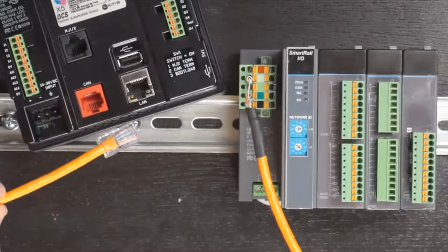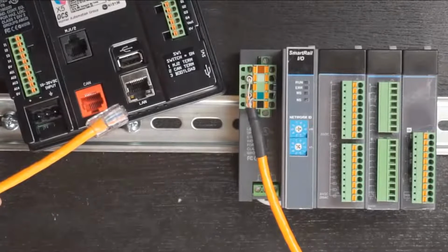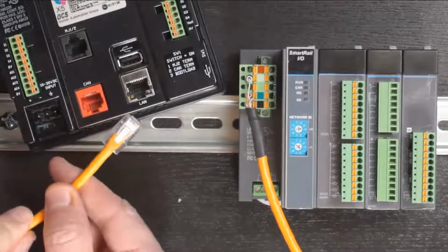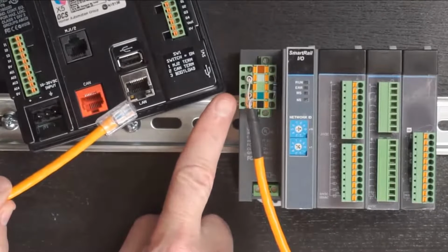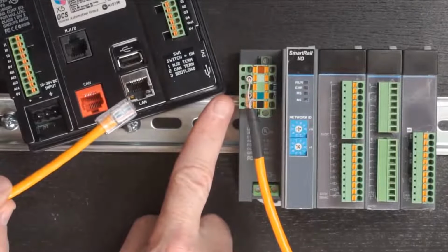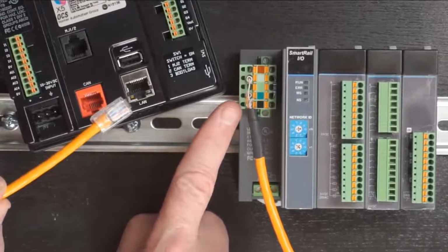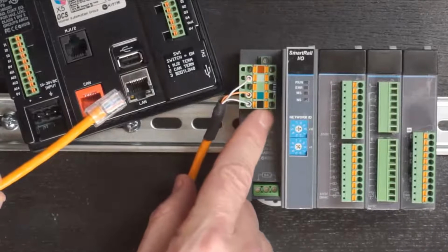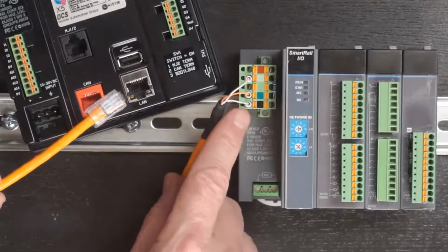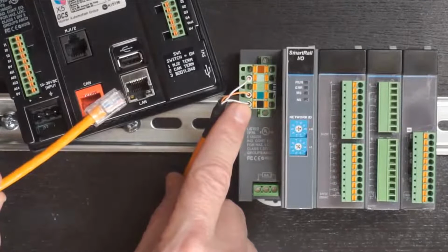So that makes it really convenient to use just a cut-off piece of Cat5 or custom-made cable that includes Cat 5 or Cat 6, with a modular jack at the end of it here. Now on this end, the double plug end of the cable, I only needed 3 conductors. I needed CAN high and CAN low, which is the orange pair, and then I still need a common conductor, which in this case, connected here to the CAN black pin, I'm using the green-white conductor. I have my choice between green-white and brown-white.